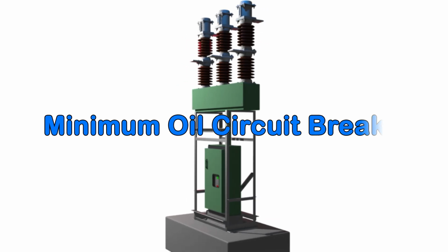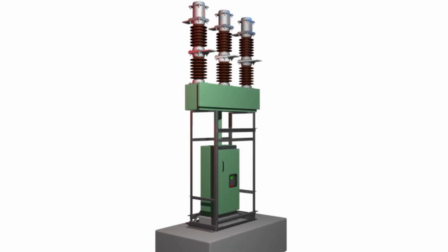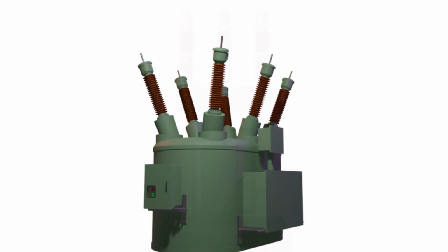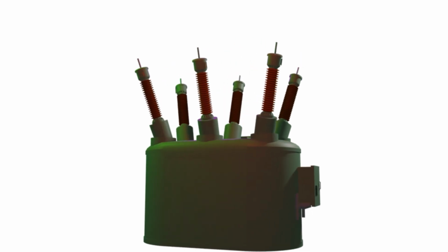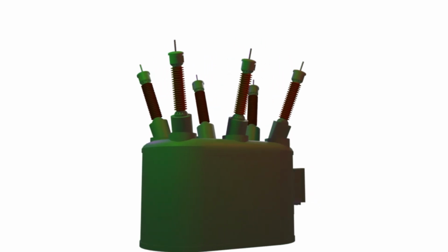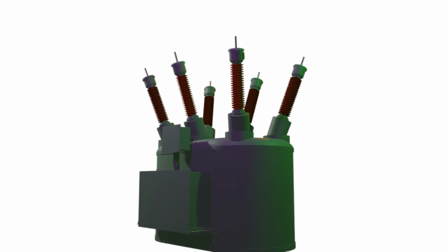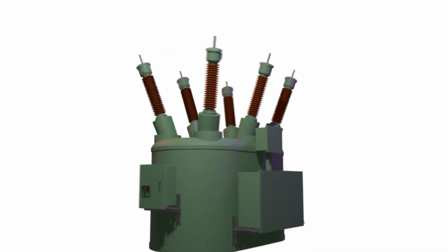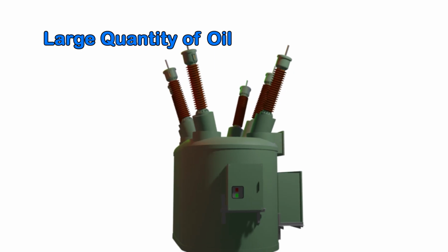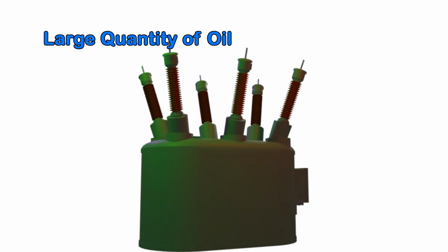Let's get started. Let us have a discussion on the minimum oil circuit breaker. Before discussing the minimum oil circuit breaker, let us recall our knowledge regarding the bulk oil circuit breaker. In a bulk oil circuit breaker, we have used oil as the insulating medium and also as the arc quenching medium. But to serve the purpose of both arc quenching and insulation, we have needed a huge quantity of oil, normally above 50 kiloliters of oil. A bulk oil circuit breaker with a 31.5 kiloampere short circuit breaking capacity requires more than 50 kiloliters of oil,